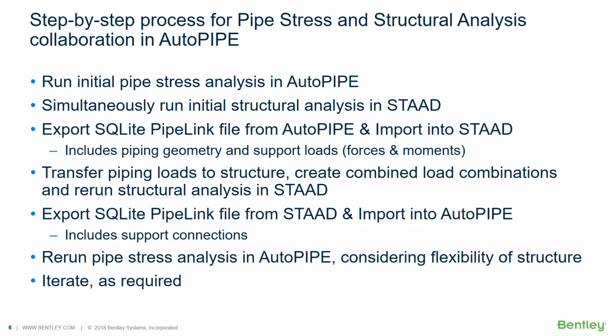We want that because that's more realistic rather than just bulking up your steel or assuming some high standard loads. But it's basically very painful to have to walk through that and manually mark up isometrics or print out different reports and get them over to the structural engineer physically. The structural engineer then has to import all of those loads, forces and moments into their structural model in STAAD. Again, manually, every single support, every single direction, and each load case. So it's a lot of work.